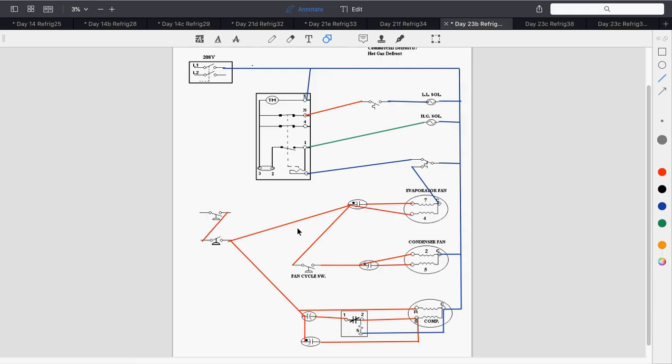Okay, now I have one more thing I have to wire. My pressure switches. Where am I going to bring those pressure switches to? L2? Yeah, basically L2. Now, I could bring it back up here, but again, when you're looking at these in the field, where it's going to wire from most likely, this is why they put this big brass connection down here. Okay, it's going to wire to there. Okay, because that way you only have one bundle of wire coming from L1 and L2. Make sense?